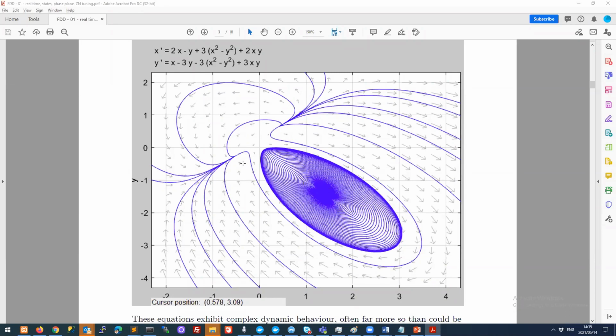And sometimes we can shift this picture. We can design a controller that actually changes the way this looks. Sometimes the behavior that the system wants to go into is the behavior that we don't want. So even though you've got this nice stable steady state, it's nice from a stability perspective, but these might be undesirable points. Maybe you get bad conversion in your reactor, something like that. And even though this is an unpleasant place to operate, this might be a much better reaction rate for you. So we want to design a controller to navigate this plane.